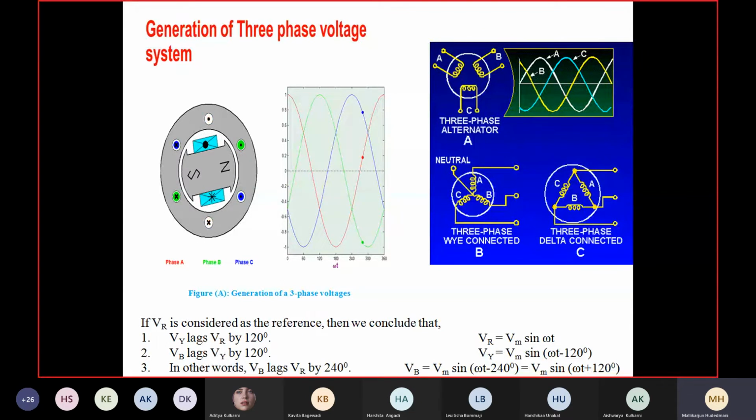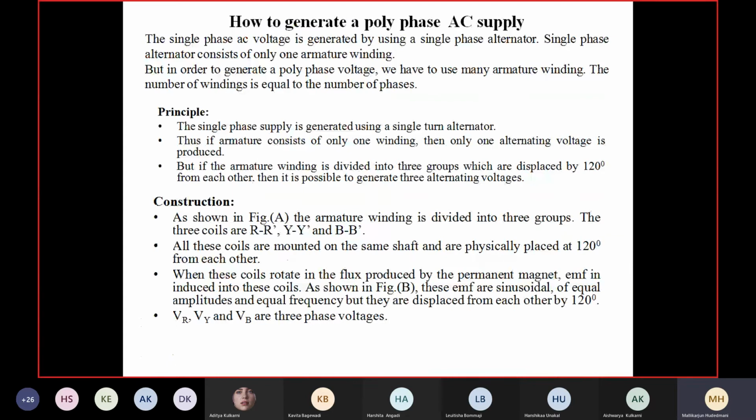Field is rotating and conductors are stationary. There occurs induction of EMF collectively in the winding, which is already wound in the three phase notation, either in the star fashion or in the delta fashion. So-called induced EMFs are symmetric in dimension if the windings are perfectly balanced. Then we will get magnitude wise similar, but phase wise a difference of 120 degrees because it is of three phase notation. This is about the generation perspective of that.